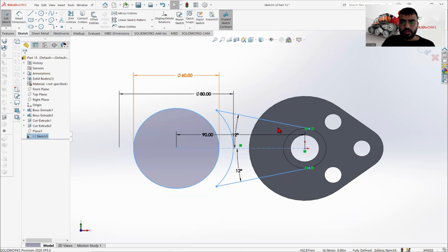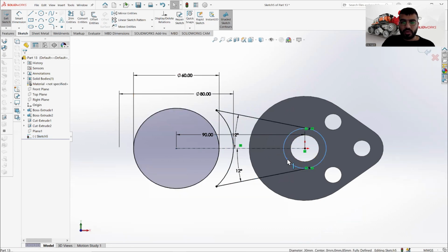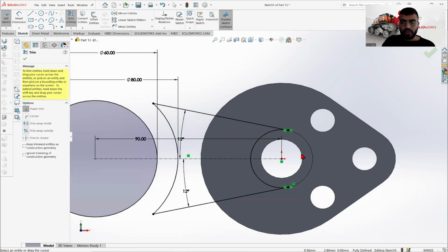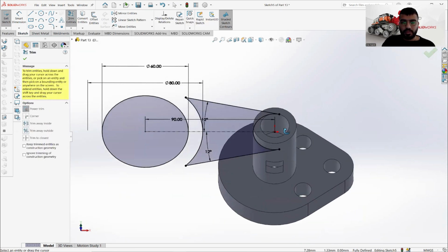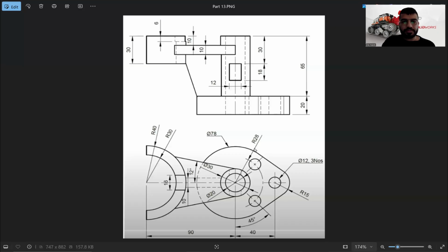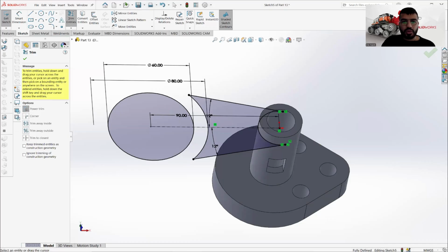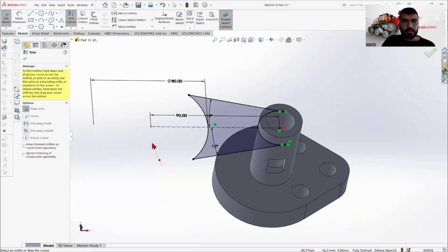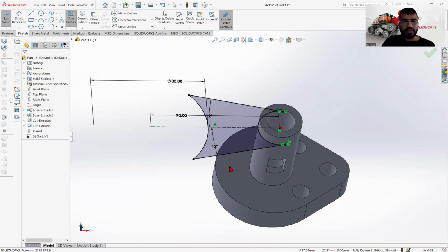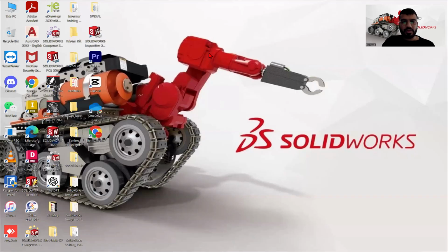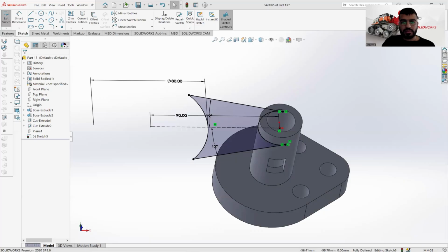Normal to. We can close the sketch here by clicking on this circle and clicking on convert entities, and do the trim there also. Perfect. Now we can do the extrude. So here it's better to remove this circle. No need for it for now. Then you draw it after, because our first step is just to do this part.